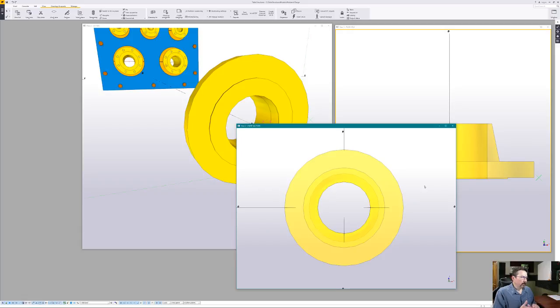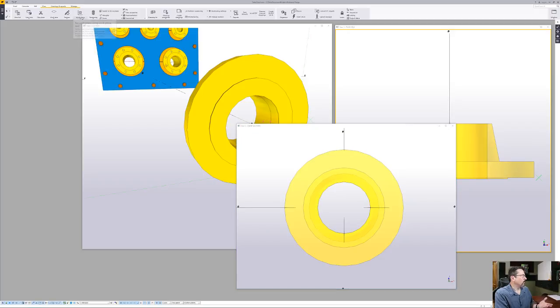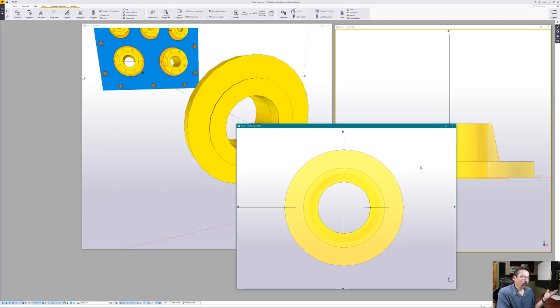Once I've created this, the other thing I do is hit G10, which sets my work plane. The other way you can do that is to go up here in the view menu to work plane and pull that down. I always use parallel to view plane, because we've just created a view plane here, and I want to create my work plane so that I'm working in this view. I want my work plane to be set to that. So I say parallel to view plane, and then you just give a point somewhere in the view.